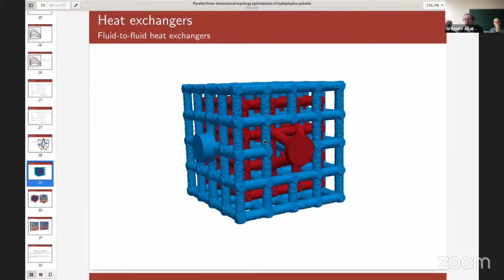But of course, since the mesh changes, the size of the discretization space changes. And so sometimes it's very hard to compare the objective function because it was computed on two different meshes. Exactly. Compared to a SIMP method or the classical level set method, where you always have the same finite element mesh in the background, here you don't, so there is a small discrepancy. Yes.